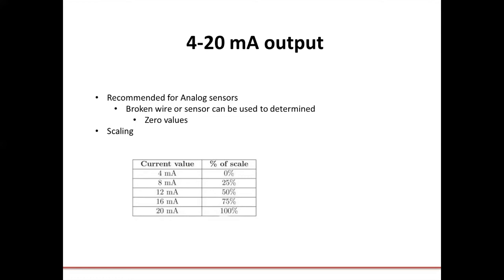But if the sensor is broken, you won't know if the liquid is still flowing or if the volume is at a certain level, because 0 is a true value within a 0 to 20 milliamp output. And same with voltage outputs, for instance 0 to 10 volts. 0 is a true value. If the sensor became disconnected, you may read 0 in your data acquisition system and still think it's a valid number. But in actuality, your sensor may be disconnected or have come loose.